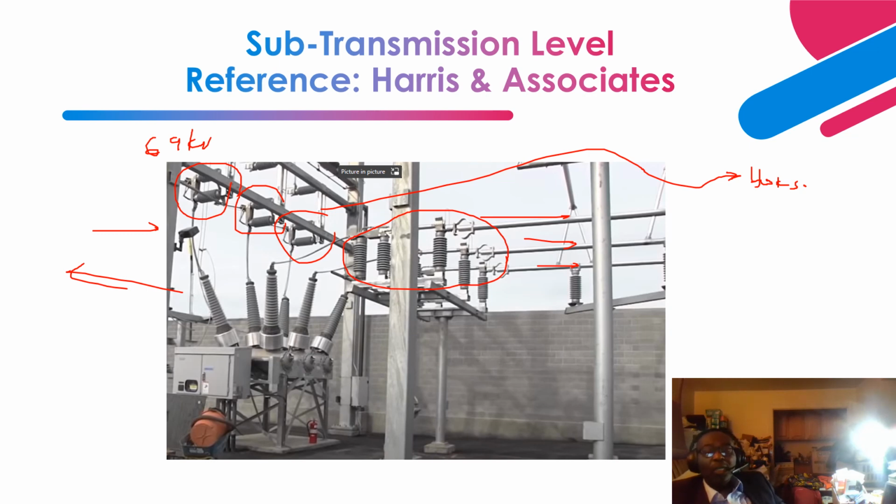So if you have a circuit breaker with a disconnect switch on both sides, you de-energize the circuit breaker, then open the disconnect switches on both sides. It's more for maintenance and safety. Similarly, to energize, you have to close both before you energize the breaker, because it is a no load disconnect switch.